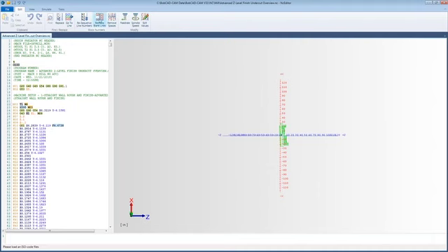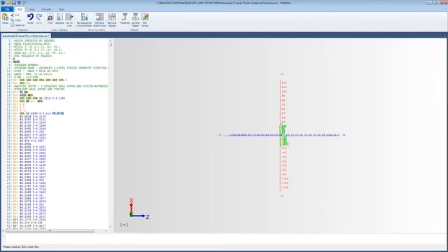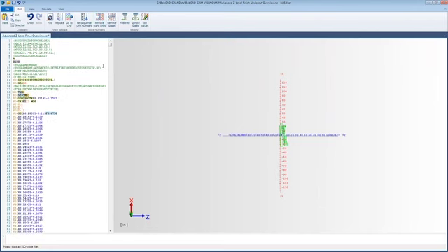You can remove any blank lines. So if your machine doesn't like having blank lines in it, you just get rid of them. And then spaces, if your machine really hates spaces, you could say remove spaces. These are all kind of options, though. I mean, resequencing line numbers, that's a big deal. Some machines won't go out of order.